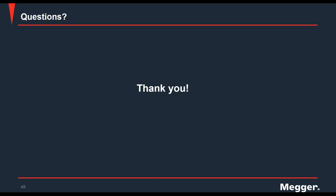All right, thank you. So, Daniel, next question's over to you. Could you please explain dual ground for us? Sure. So this is a term typically used, it's not restricted, but typically used when talking about testing high voltage circuit breakers, right? We know that for safety, part of the process of isolating the circuit breaker is having both sides of the circuit breaker grounded, right? So in any measurement you want to do on your circuit breaker, you have to make sure it's isolated and grounded on both sides.